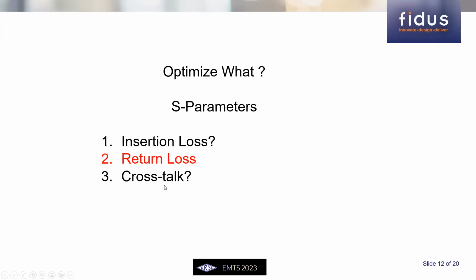And we also have a category of crosstalk. I'll not be addressing crosstalk here. Crosstalk deals with a system of nets and how you isolate them. So that's not being considered here. So the focus is primarily on return loss of a very high speed data transmission. And the simulations, again, are done using ANSYS HFSS, which is the full 3D EM solver version.